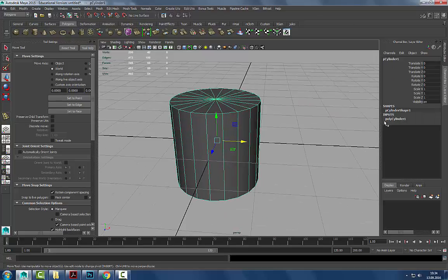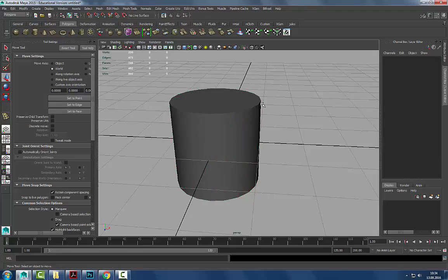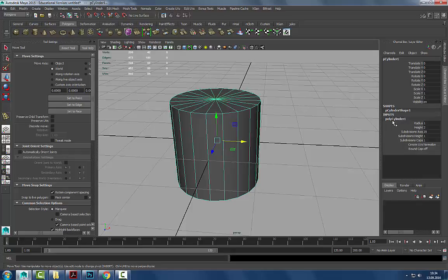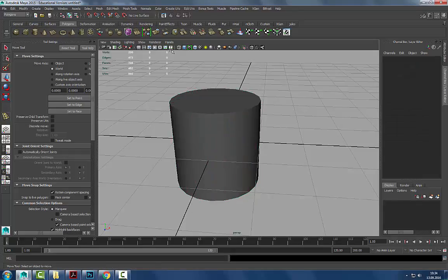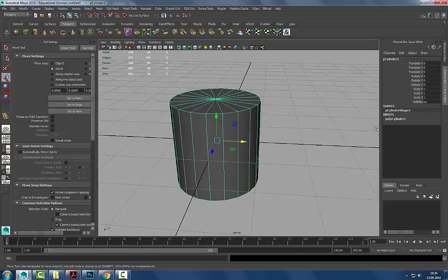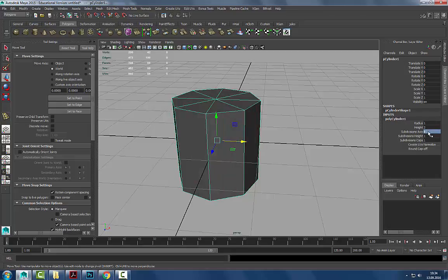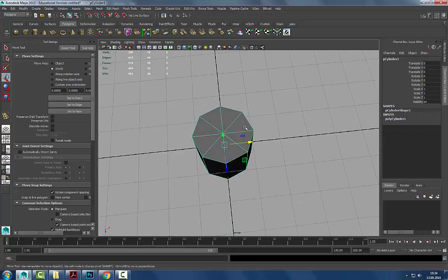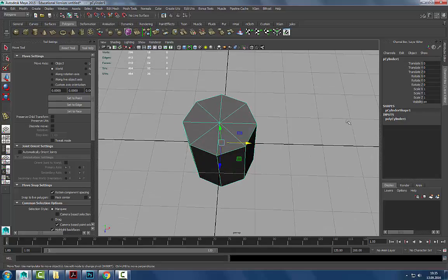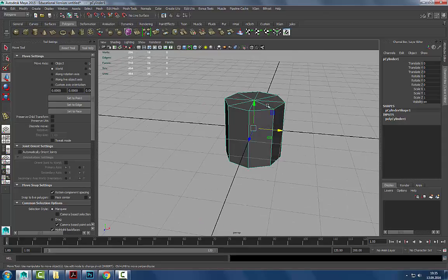And typically, when you're dealing with circular objects, you might say, yes, this looks nice. It has enough definition. Wonderful. But when you're working, it might be better to intentionally lower the resolution so that you're not left with too many of these edge loops. So I can go into the input and I can just enter 8. So if we keep this to even numbers, typically the way to go. I think you'll find often that 8 is a good number for subdivision axis in circular things.